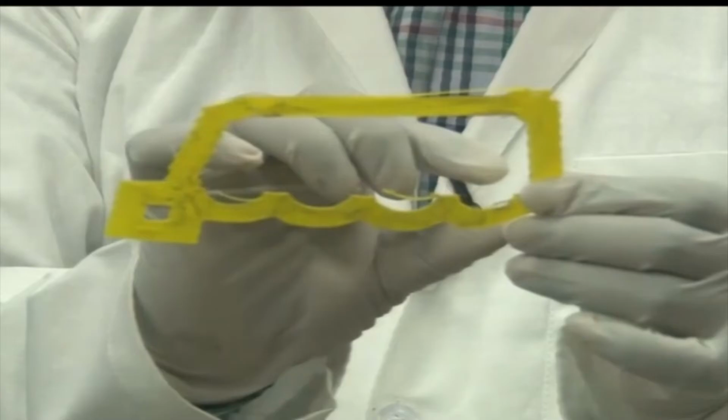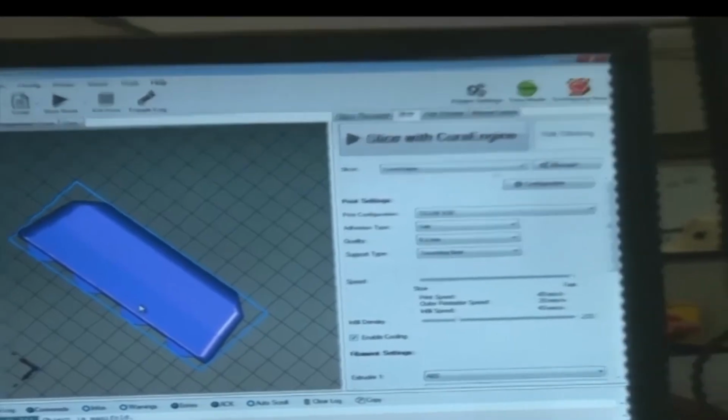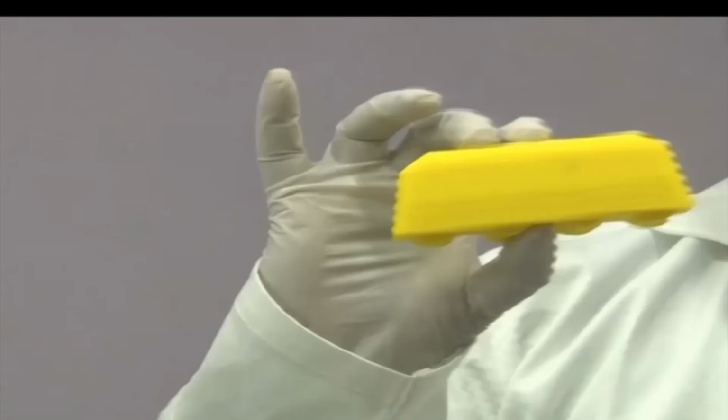So we are talking about selecting brim here in the software. When the nozzle head starts printing, it prints the actual model that we want, but it will deposit a little extra material to produce this first layer. This is actually the brim. This is the model that we have, this is the model that is produced.